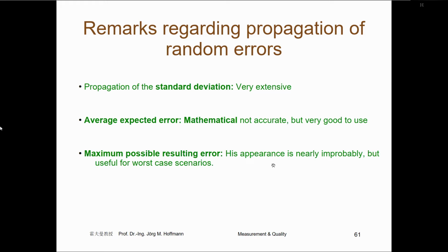And the more input values you have, the rarer would be the possibility that all the errors have at the same time the biggest value from all input measurement values. But theoretically, it would be the worst case. And when you have security calculations, then you should use this possibility for the maximum resulting error.